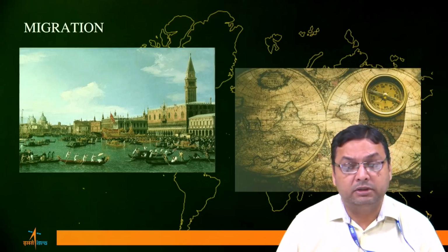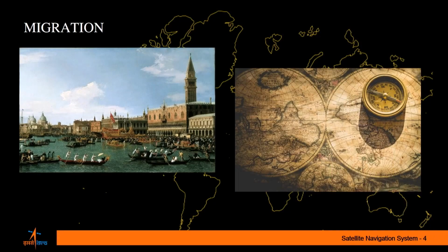As part of the exercise of the map, which is also required for movement or navigation, satellite navigation gives a very good control. Basically, it provides us the framework for the map projection and computation of distances or elevation based on certain datums. In the case of satellite navigation, we are using the WGS84 datum as the reference datum, because that is the best fit curve we are currently using for the Earth.